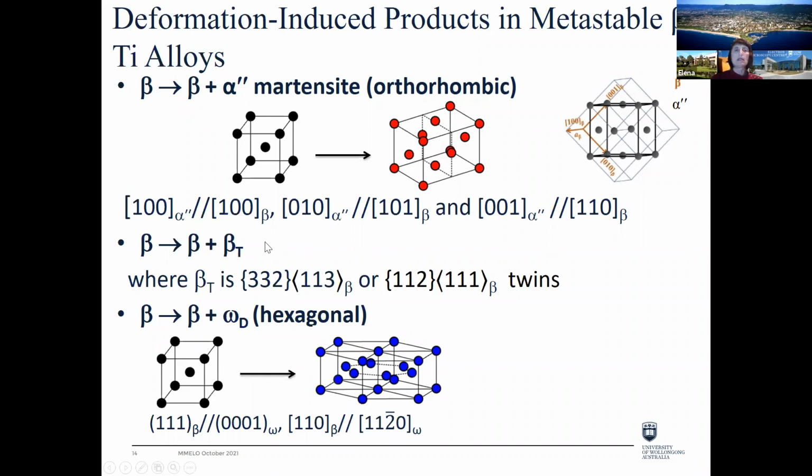The next is again twinning, and in reality, what we learned a lot on steels was the driving force to study more what's going on in beta titanium alloys. For sure, there is a difference in that in TRIP and TWIP steels we're mostly dealing with FCC as a parent phase, while here we're dealing with a BCC parent phase.